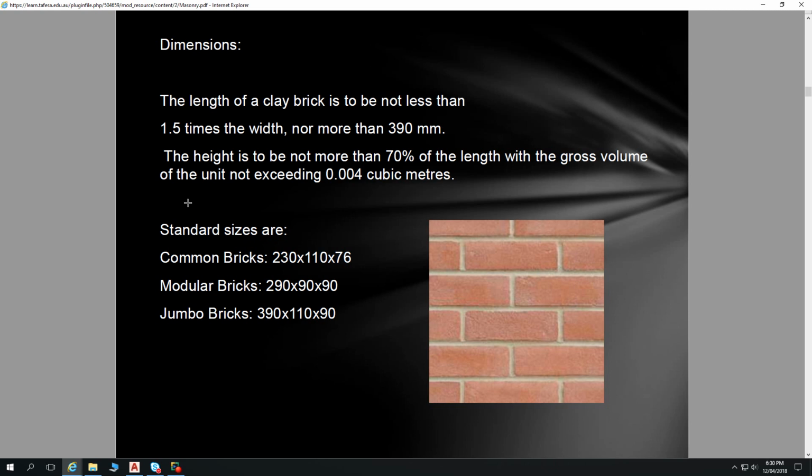300mm popping up there all the way through building. Ceiling heights, 2400, 2700, so 2 or 3 meters, very standard ceiling heights. Once again, all increments of 300mm. So to have a brick, which is also, once it has its 10mm mortar gap, an increment of 300mm, works very well with building as well. So that's why it was done.